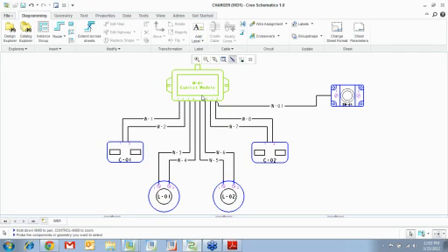Now we would take this diagram and export it as an XML file, and we will import this XML file into the cabling package into Creo Parametric, and then route the cables. Now, there are two important things that we need to be careful about. First thing is, how are we going to map this particular symbol to a component in Pro Engineer, or I'm so sorry, Creo. So how are we going to map this symbol to Creo?